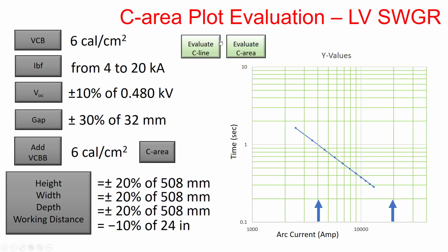Of course, if we evaluate this line against an overcurrent relay 51 function, we can see that it actually passed the evaluation, no problem. This single combination of parameters only allows us to see one possible outcome of the arc flash within this piece of equipment. Of course, as we now know, there are multiple outcomes, multiple possibilities of the arc within that equipment.